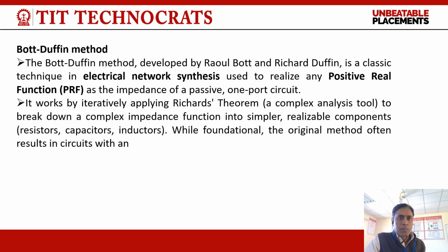Now, Bott-Duffin method. The Bott-Duffin method developed by Raoul Bott and Richard Duffin is a classic technique in electrical network synthesis used to realize any positive real function as the impedance of passive one-port circuit. It works by iteratively applying Richards' theorem to break down a complex impedance function into simpler, realizable components. While foundational, the original method often results in